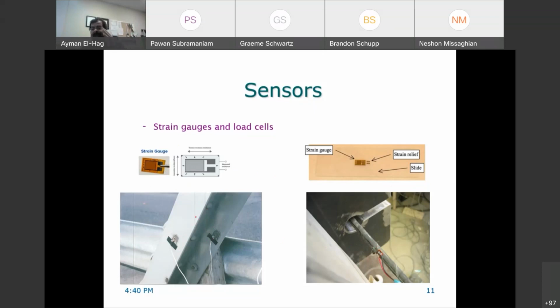This deformation is a physical phenomenon, but how to measure it? We need to have an electrical signals coming out of it, and we'll see what is this electrical signal and how it is generated, what is the physics behind that. This is why you see two wires here. These two wires to do the electrical measurement.